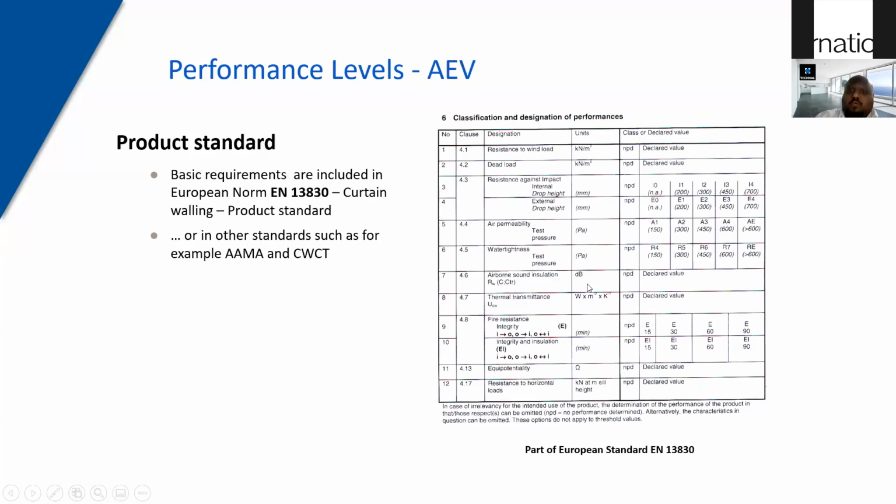Airborne sound insulation, what should be the right dB? Generally you hire an acoustic specialist who comes and does a simulation and identifies the hotspots in a building. Perhaps the building is next to an airport, perhaps the building is next to a highway. So you might have noise more prone on the ground floors and reducing as you go up. Maybe your building is in a city center and then you have noise bouncing back between buildings. So that's again a value which you have to look for.